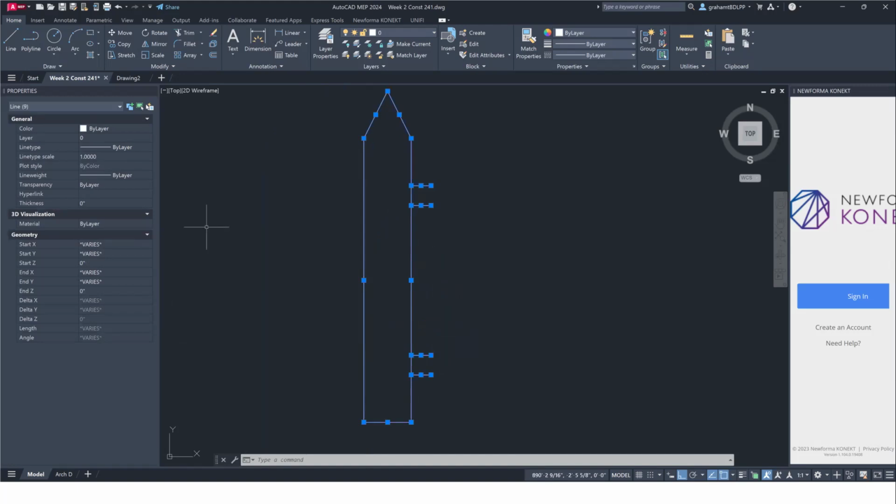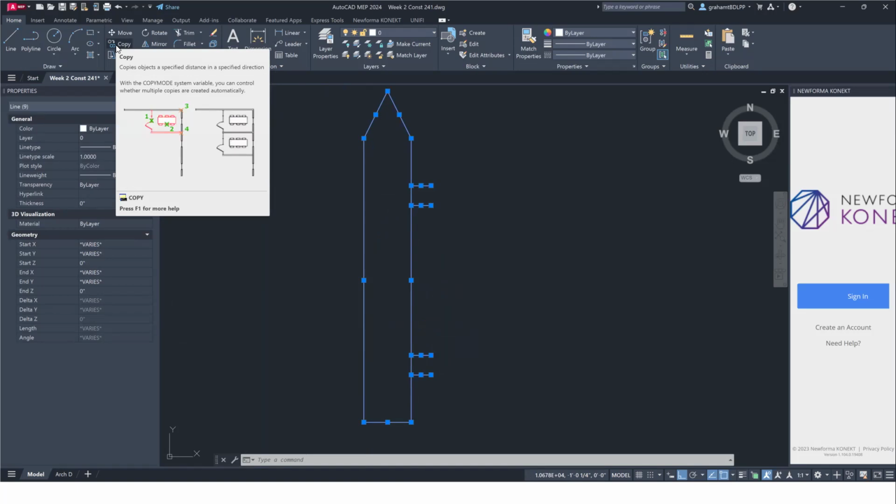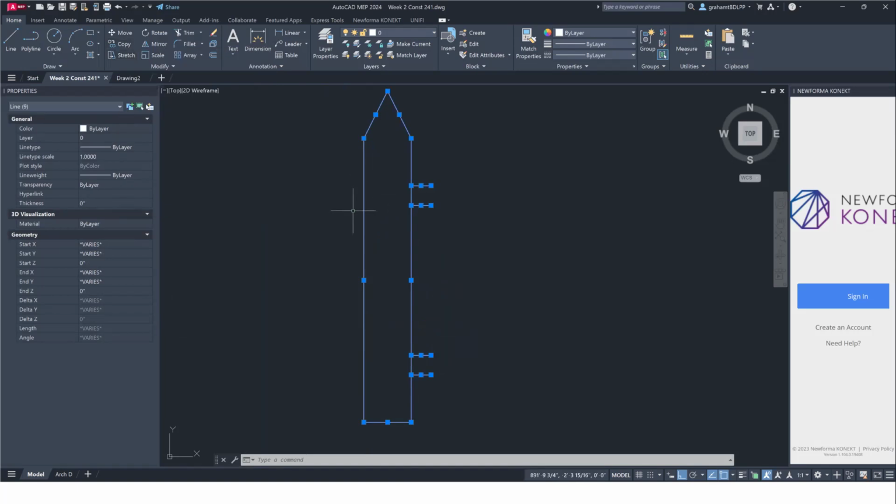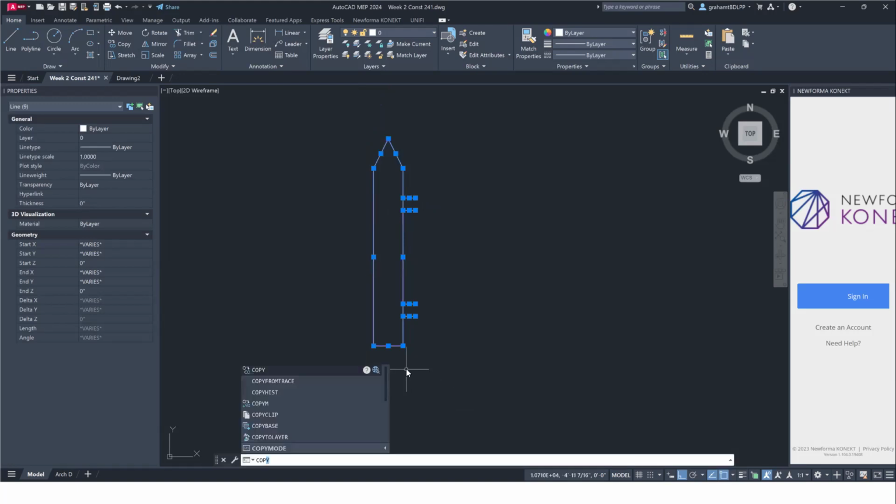Okay, so we're going to utilize the first command, which we've utilized before with our title block. We're going to copy this thing with a base point. Now, one thing, if you're paying attention, we had a 6-inch post and a 2.5 inch space, right? For a total of 8.5 inches. If you did a 4-inch post, you need to change this to moving it 6.5 inches, right? Instead of 8.5.